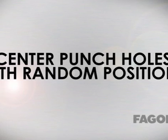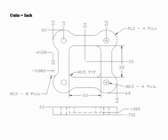We are now ready to program and machine our second operation. From our demo part print, you will see that we have 4 defined holes with center locations. We would also like to add a 5th hole at the center of the part as a pilot hole for our future pocket. Our tool for this operation is a 1/2 inch diameter spot drill.